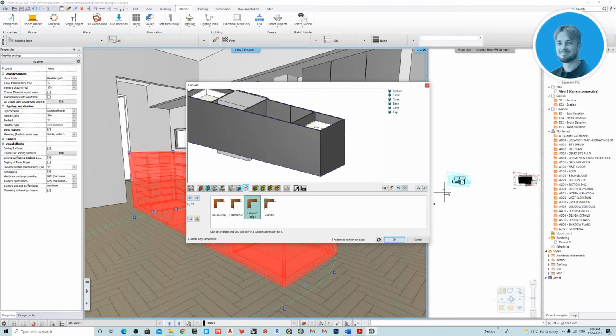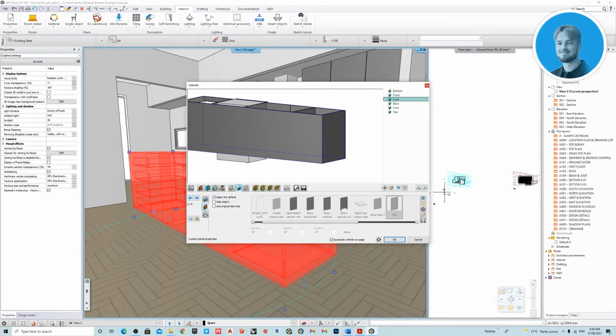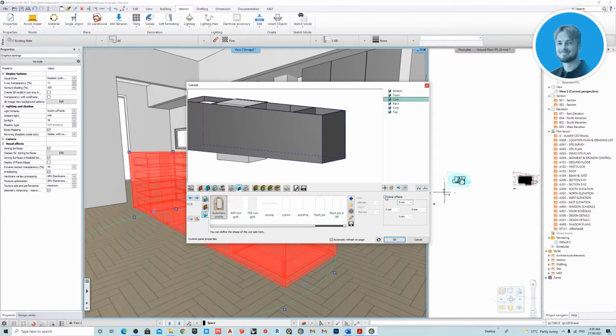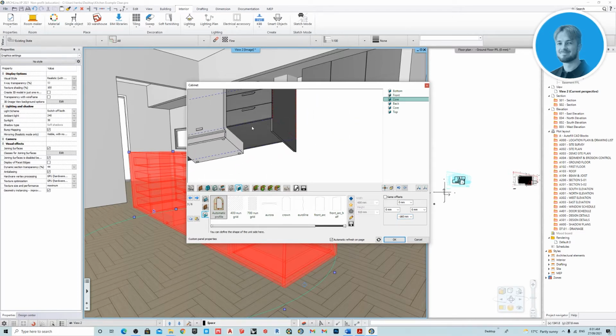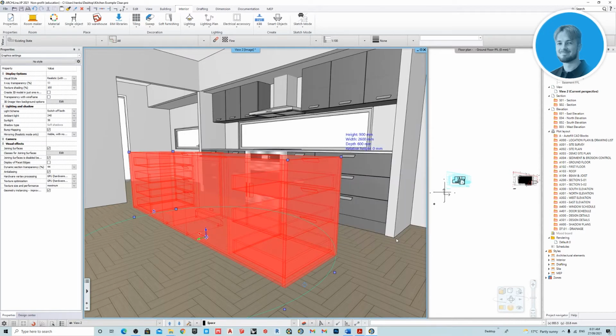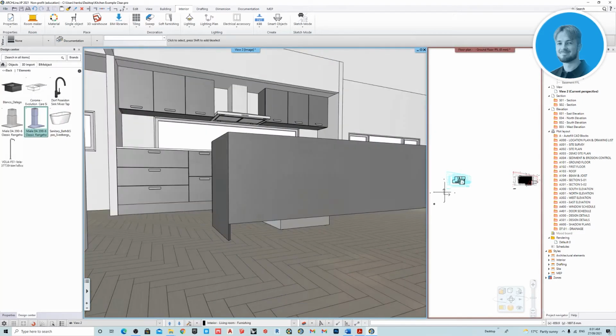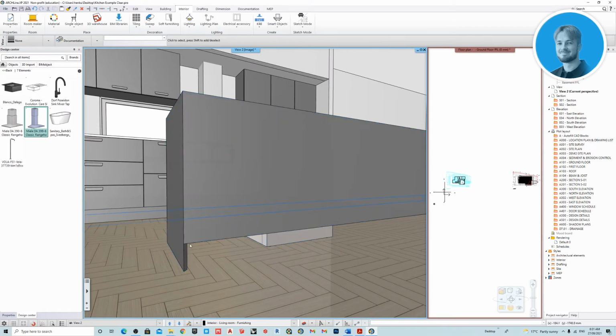Alright, now just for the side panels, I actually want them to go down all the way. So that's where I'll make those updates. Okay, so for these custom offsets, I'm just going to change this bottom one to -160. Okay, and again, that will be the bottom panel, which should be 140. You can just have a double check. Okay, if we just click OK. Yep, so that would be 140 mils. So that's extending down from there.